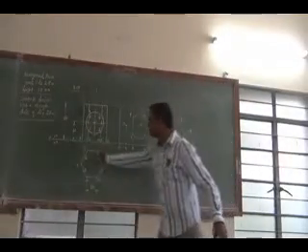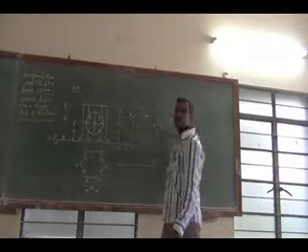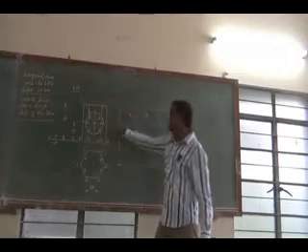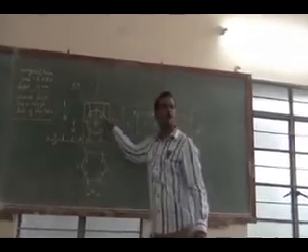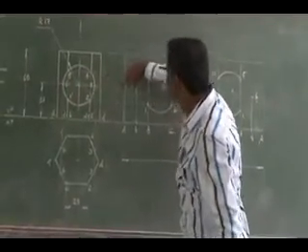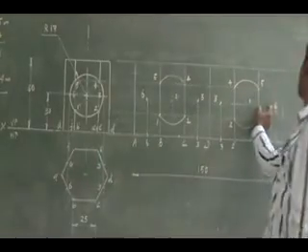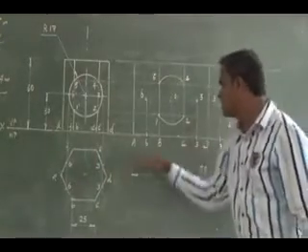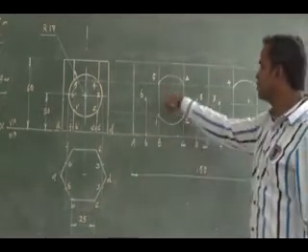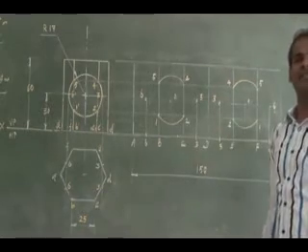So either you can transfer these distances, A to 6 distances, to the base or directly to the central projector line you have drawn. Right? From A to 6 you can directly mark it. The 6 and 3 fall on the central line. Similarly, from F to 6 I can directly mark it. Otherwise, as a procedure, it falls on the base. So you mark it on the base, then you project it to the central location. That is going to be the exact location of the cutting points 6 and 3.